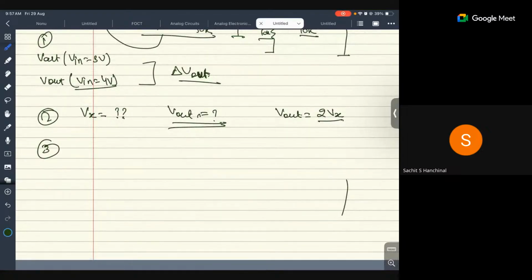Now the third part is that if the open loop op amp has a DC gain of 10 to the power 6 and open loop resistance is 1000, calculate the change in output voltage when the load current goes from 0 to I load. Now we have been given an open loop resistance also, 1000, and I load will be changed from 0 to 40 milliampere. So first we assume that there is no current going. Like I'm just saying that this is a completely black box.